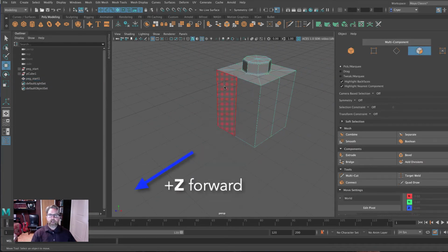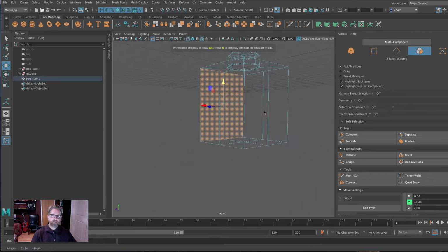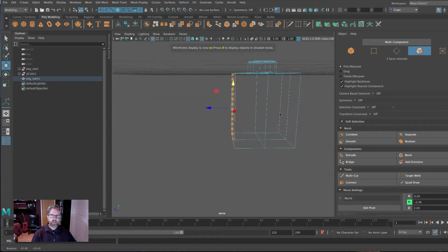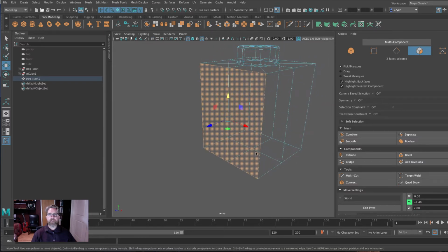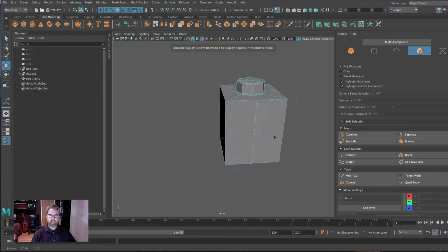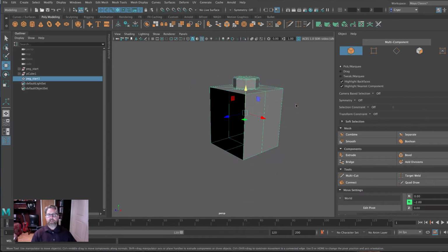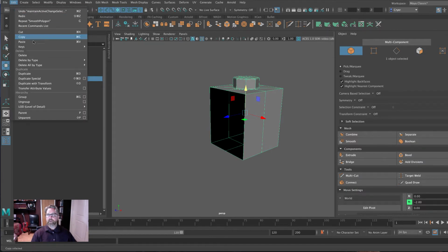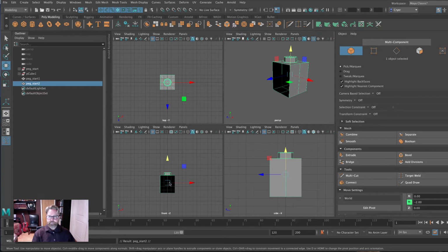And we'll delete these faces. Whenever you're deleting faces, hit the 4 key. Make sure you don't have something on the other side. If you hold the Control key, bounding box deselected, just select while maintaining your proper set of faces. We'll delete that. We'll hit the 5 key just to take a look at that shape. Right, so there it is. And we'll duplicate it. We'll come to Edit, Duplicate.